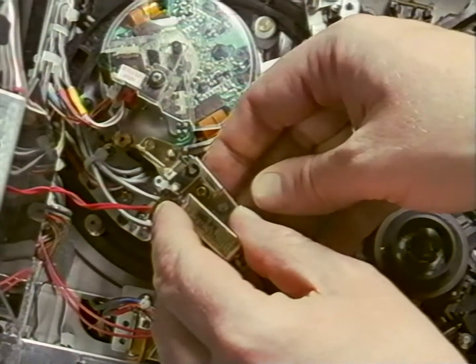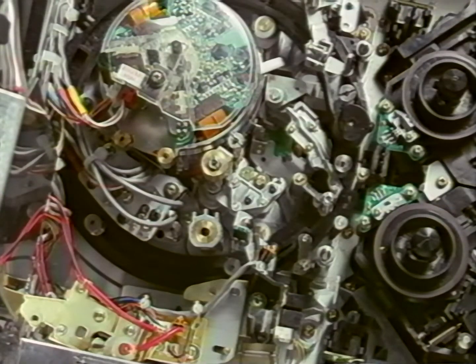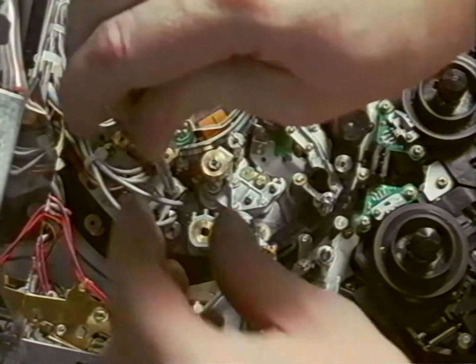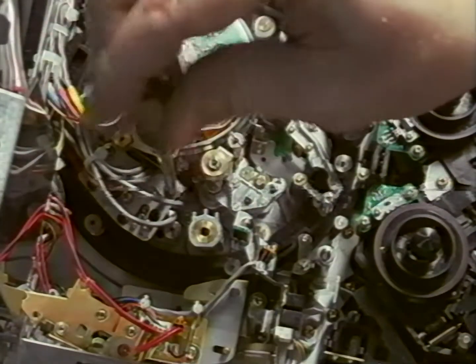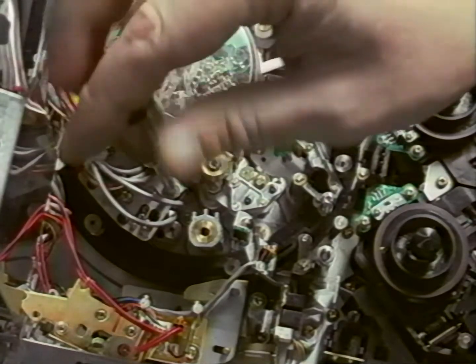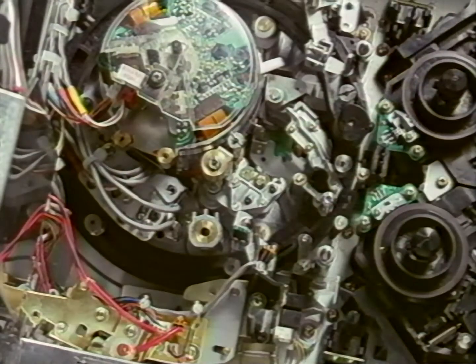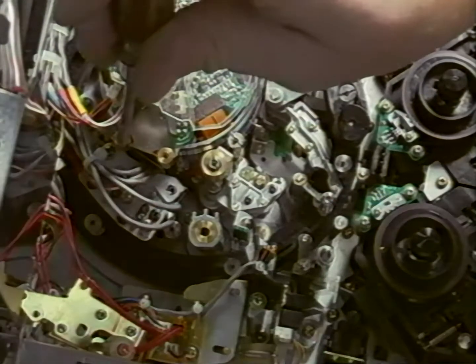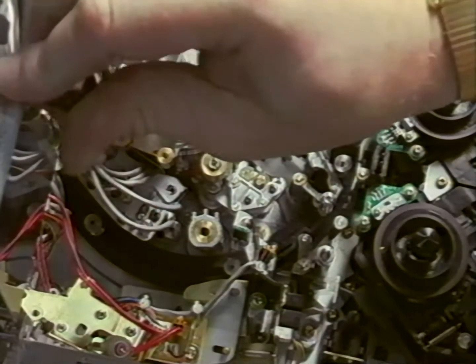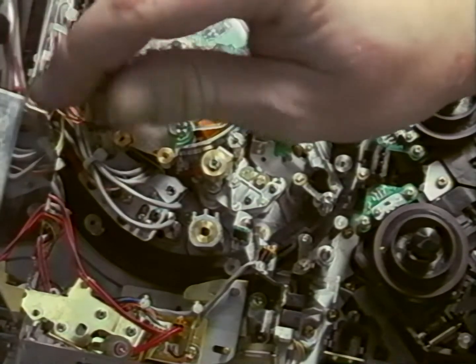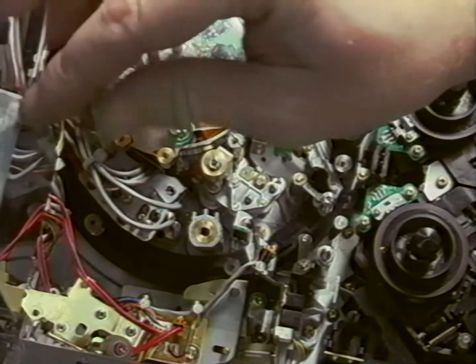On this tape, we are removing the assembly as one complete unit. The advantage is that there is very little time spent installing and there is almost no alignments necessary. Now that the cleaning roller block is removed, the top of the audio block assembly can be reached. Remove the 2 fixing screws securing the holding plate. Remove the holding plate. The audio assembly can be lifted out.